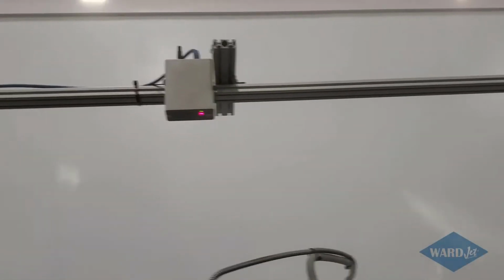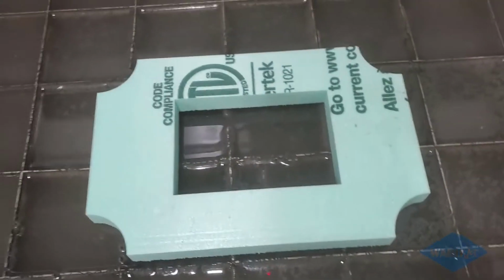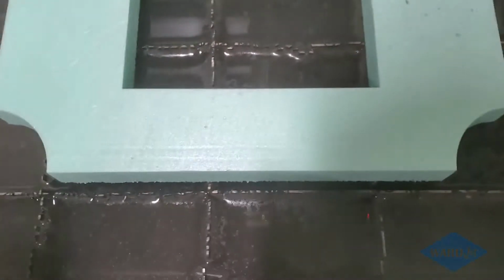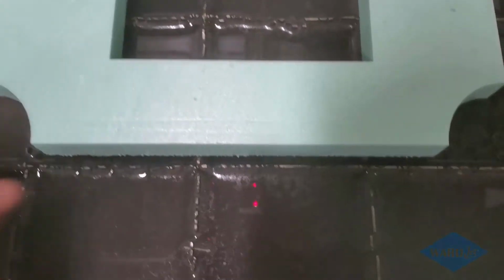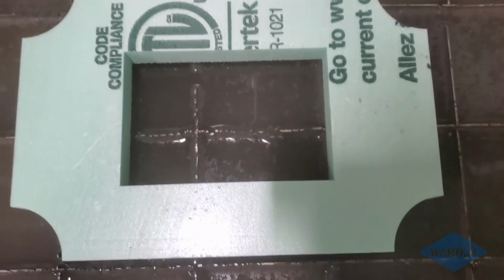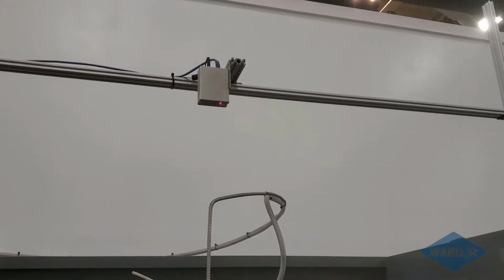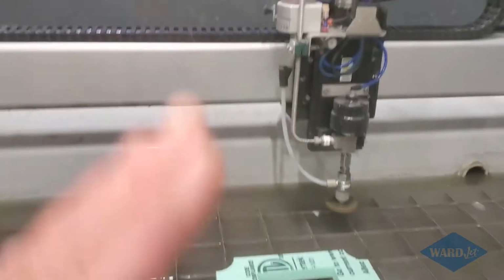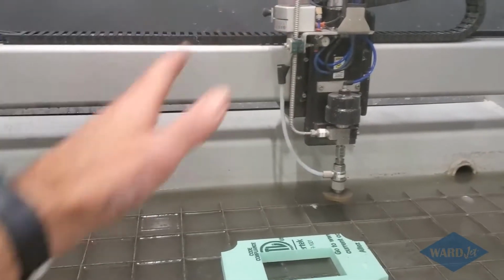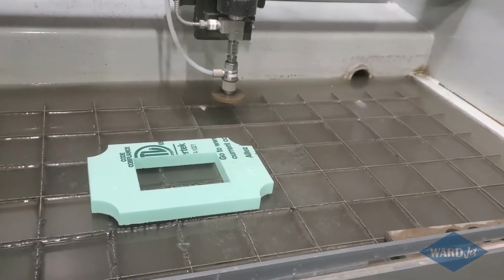So, we've got our IGEMS camera up there. We've got our template that we're going to make a part of here. The straighter that you can get this on the table when you take the picture, the easier. You could cut a straight edge and then butt this up against this to make it a little straighter, or you can make the adjustments in CAD. So we've got a calibration process that we go through with the camera, so it takes care of any sort of keystoning effect that you might get towards the edges of the cutting envelope.